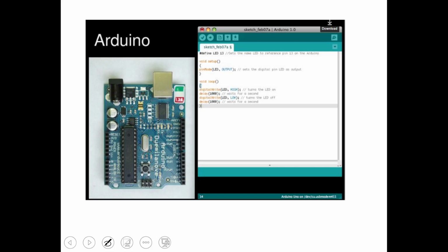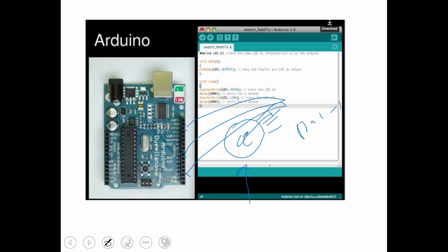Okay, so what will happen with the smoke sensor? There is one smoke sensor, and when someone is smoking here, it will detect it. Suppose the sensor has 3 or 4 pins, and we have to integrate these pins here. We have to assign each pin according to the pin diagram, for example, pin 1 is assigned to LED, 0 volt, 5 volt. This is the coding you have to do here to integrate with the Arduino.